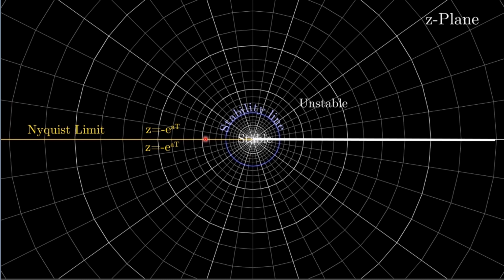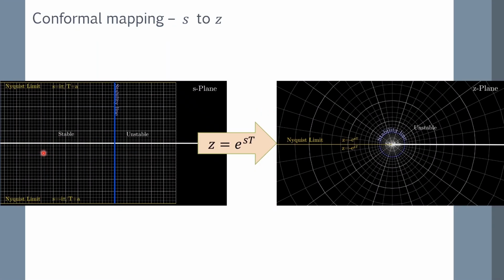So this is a very interesting thing to note, because it basically means that we wrap the frequency domain of the S-plane into another plane that is also full, but now can actually have a multiplicity of frequencies. We're gonna discuss this later, but this actually spirals in, so you actually get several copies of the same frequency in the S-plane. So this mapping that we discussed in this animation is called a conformal mapping.